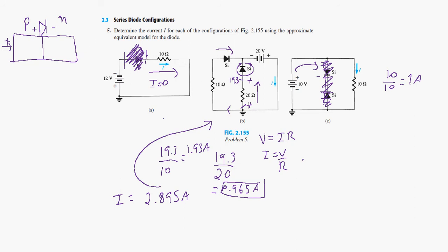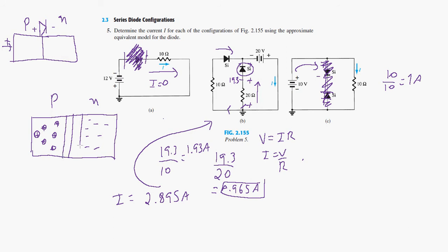Okay, so as you can see here, we need a forward bias on a diode for it to be open. So if we want to revise the structure of the diode, we have the P side here and the N side here. For the P side, we have holes which are the charge carriers here. So they have positive charge. Each hole has a positive charge. On the negative side here, we have lots of free electrons, and this diode will have a depletion region here, which on this side is positive and on this side is negative.